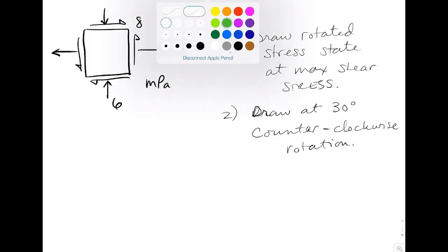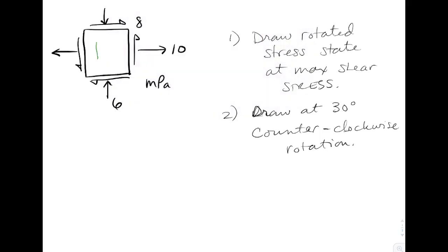So we're going to focus on the Mohr circle approach, but we'll set up the equations. So we need a coordinate system to do this. If we were to put this into the tensor on the x face, we would have positive 10. On the y face, normal, it would have negative 6.